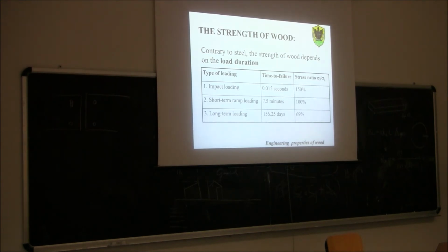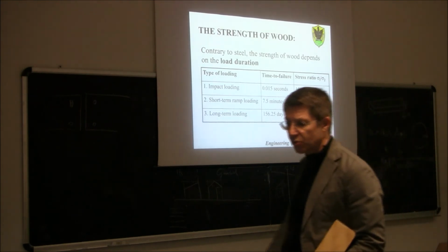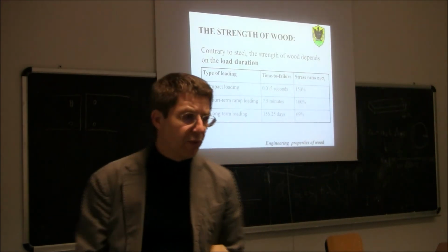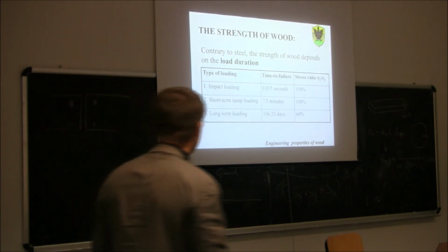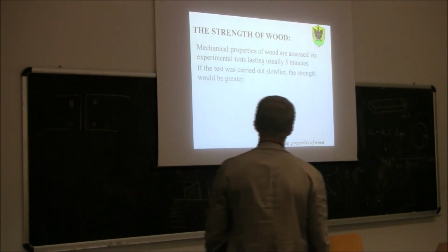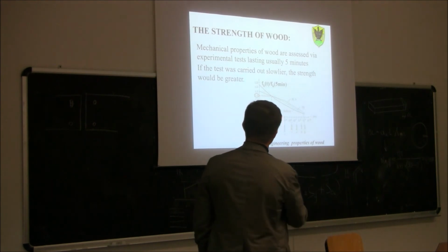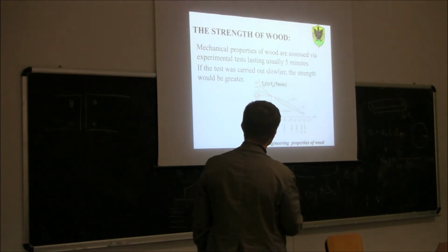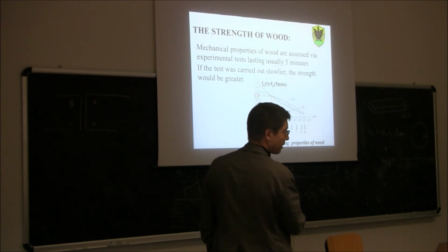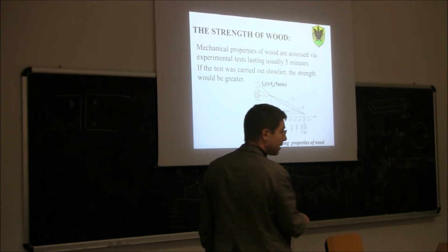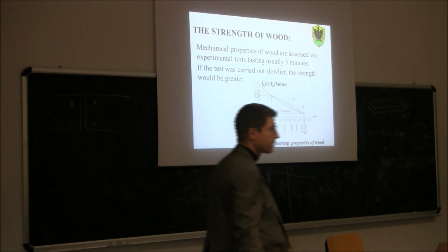As I was mentioning on Monday, this property is typical of wood and of another material, glass. Also, the glass has the same kind of behavior. If you load it fast, you get a stronger value than if you load it very slowly. You see again this plot here: 5 minutes, the ratio between the strength and the strength over 5 minutes obviously is 1. 1 second, 10% more. In 50 years of load application, 40% less.